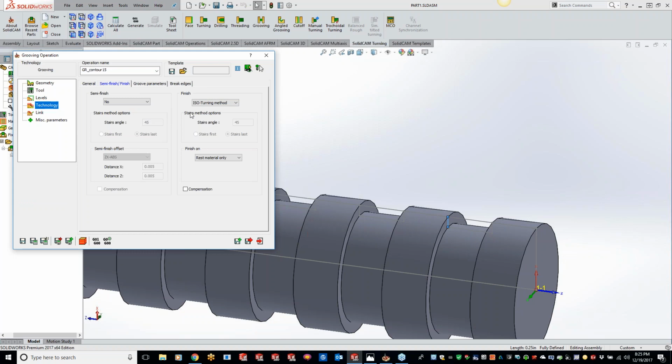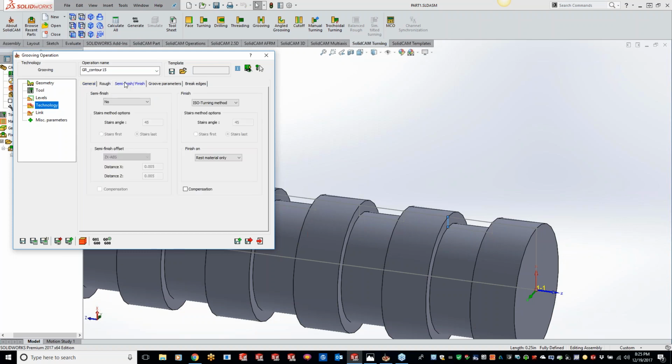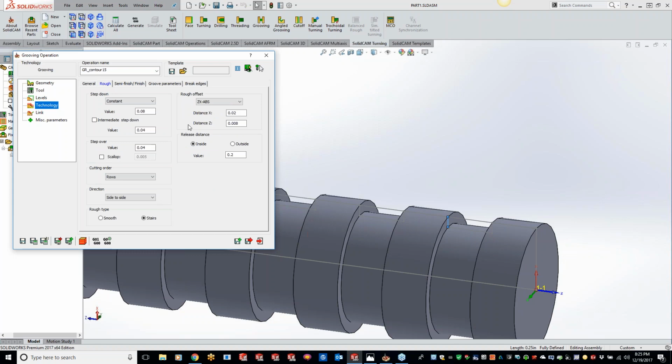Okay, so we have the ISO, oh, you know what, I'm going to have to turn on roughing too, because we get a little too much material in there. So let's kick this step over to 200 again, and let's do 150 step in.